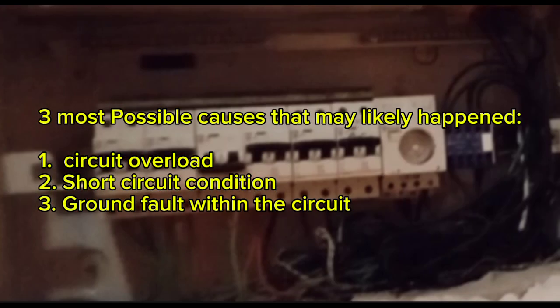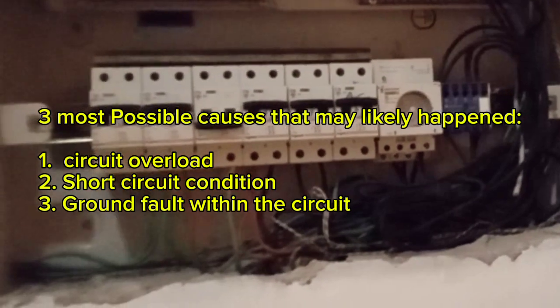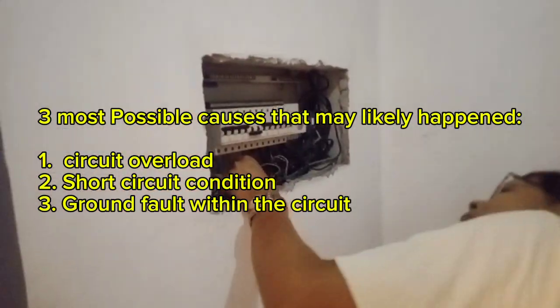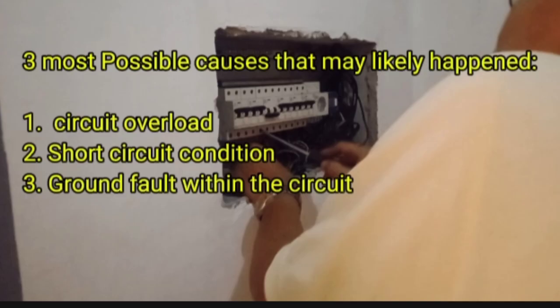In order to avoid tedious and repetitive work, by elimination method, I have reduced all the possible causes into 3, which is most likely to happen. A quick assessment on the total connected load in the circuit shows that the circuit is not overloaded. Now I have reduced the possible problem into 2.